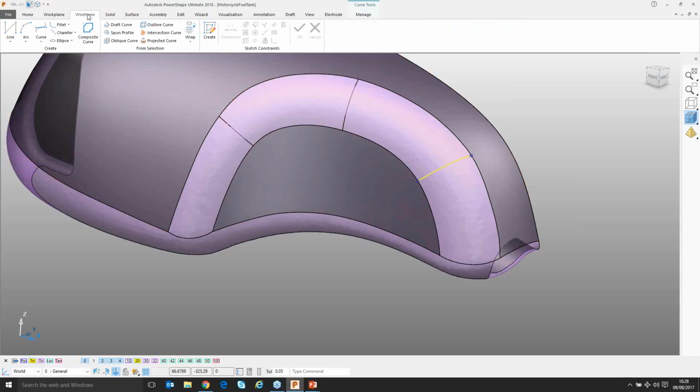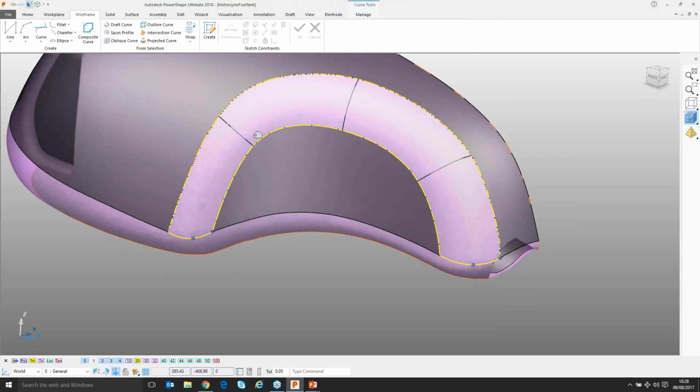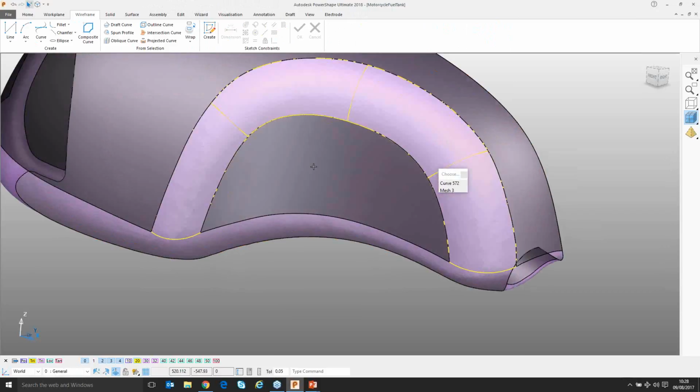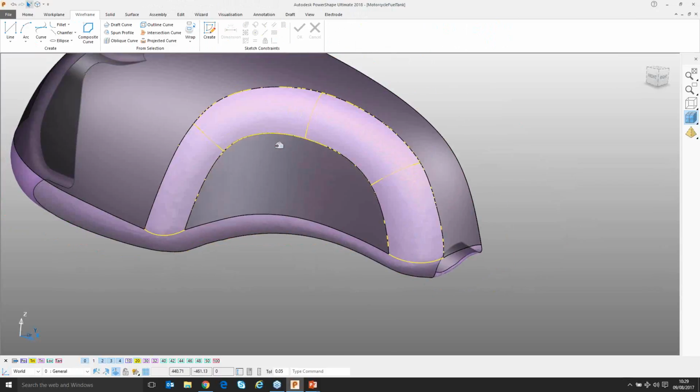And then I'm going to ask for a composite curve around this edge. So let's quickly record around, and this is important because I'm grabbing the edge of the surfaces and I'm grabbing the topology, the information about the tangencies and so on from the edge of the surfaces as we go round. At the same time, it knows that we're on a triangle set. So when I select these internals as well, what we basically have selected now is that wireframe composite curve around the edge and these internal curves that I drew over the triangles.